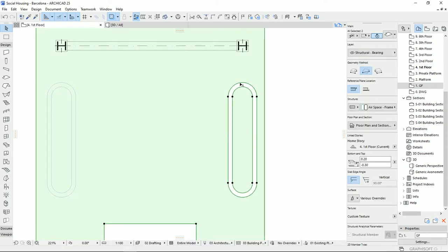So what if I want to have a different slab here in the middle? I'm going to select the slab tool again, holding down the space to recognize the area, then one click, and it will draw the slab for us. Then I'm going to select this one, and then clicking on this node, subtraction, and then by holding down the space, I can subtract the middle part. Now the slabs look like this.